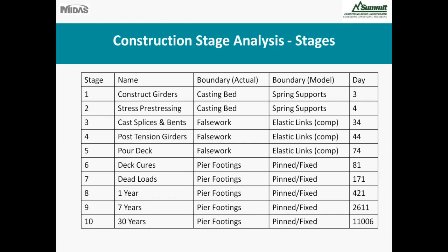On the construction stage analysis, the stages 1 through 10, we constructed the girders, stressed them in the bed, then erected in the field and casted the splices and the bed caps. Post-tension, poured the deck, allowed the deck to cure, superimposed the dead loads, and then aged to 30 years. Then, of course, there were the moving load analysis and seismic load analysis on top of that.